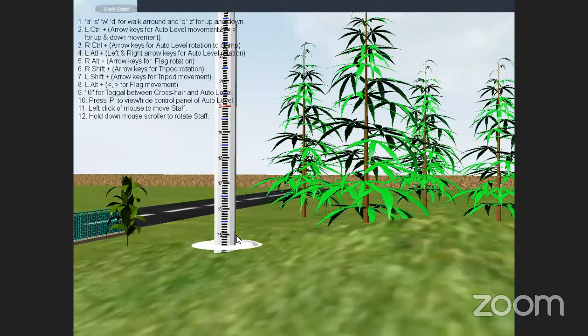Okay, this is the way you are going to do back side and intermediate side, foresight, then back side, intermediate side, and foresight, based on the requirement, and you are going to note down the values in the level book. The entry of the leveling values, the back side, intermediate side, and foresight values in that book is called the level book. The first column is station, back side, intermediate side, then foresight, then the height of the instrument, then the RL of the points, relative elevation, then remarks you are going to write. Now I will explain the tabular form over there. Okay.